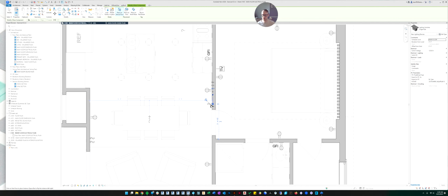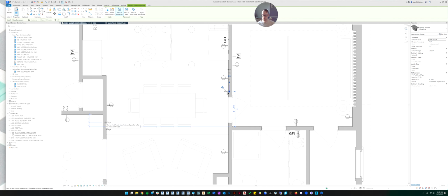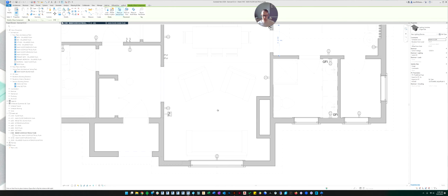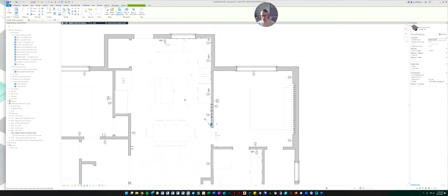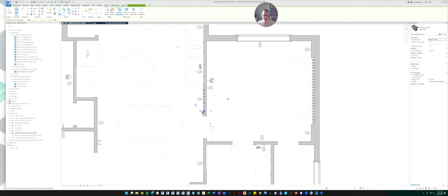If we did the dining room table light, we'd probably want to be able to switch it from this location or this location. And then again, if you had put your light in here, you'd probably add another switch. So you're going to get a lot of switches stacked up over there. For now, we'll just worry about the lights we've put in. And then in here, we'll do a switch for the pendants and a switch for the can lights.